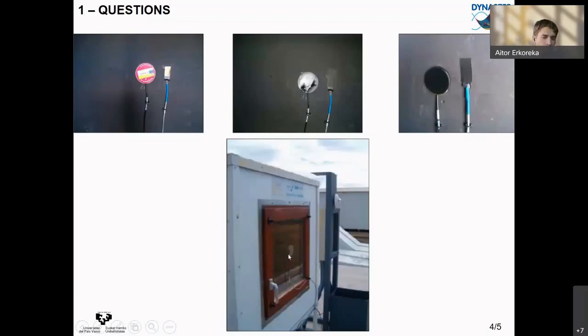So the temperature measured by this surface sensor during the daytime, when solar radiation is striking the window, will probably be different from the real glazing temperature. Why? Because the glazing surface has a different emissivity for the long wave radiation than the temperature sensor, or the round one, the heat flux sensor.